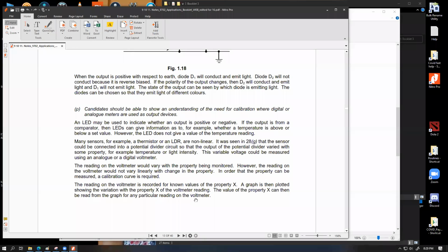If you still find it a bit difficult, I can make it easier. Think about how thermometers work for us. Whenever we calibrate a thermometer, we don't mark it for all the temperatures that we might measure. We keep the thermometer in melting ice and mark it as 0 degrees Celsius. We keep it in boiling steam and mark that as 100 degrees Celsius, and then we divide the entire space in between into 100 equal spaces, where each division represents 1 degree Celsius.